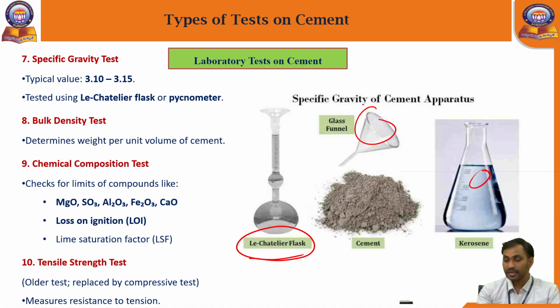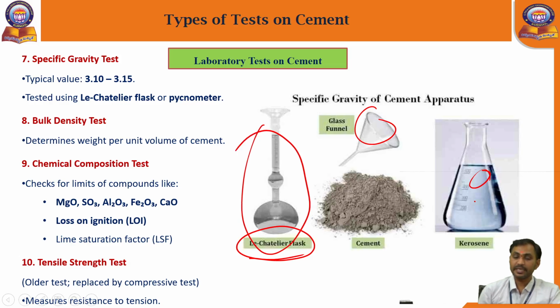Kerosene won't change the reaction. So the specific gravity test is conducted by placing kerosene in this Le Chatelier's flask.